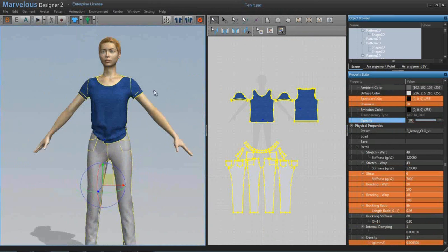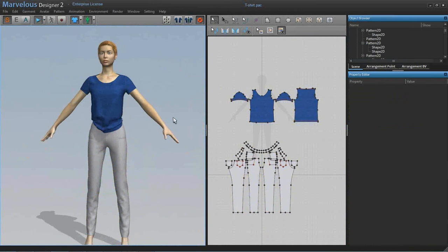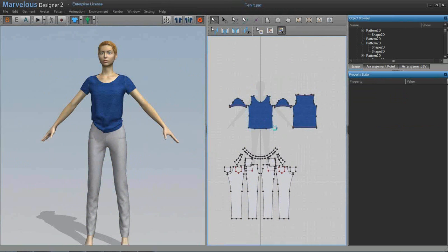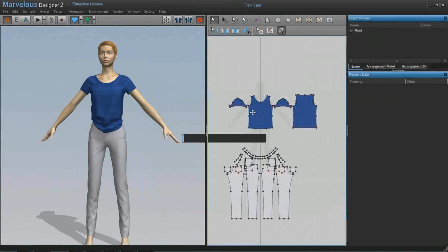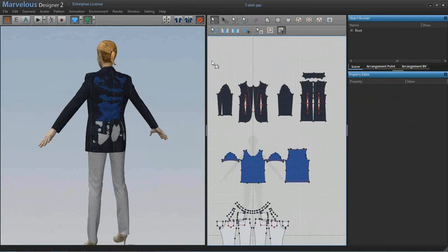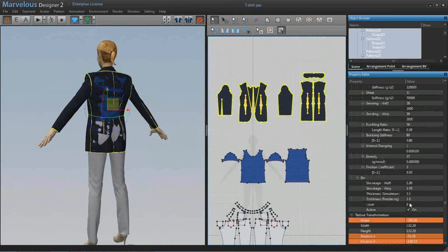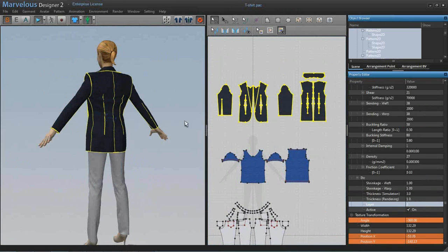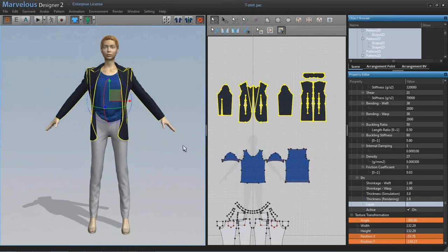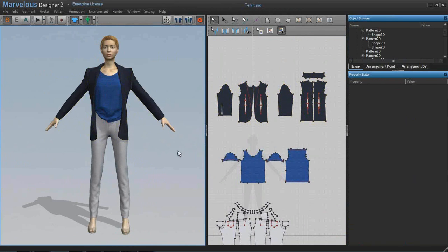Okay, I layered the 2 garments, and if there is enough space between garments, you can add more and more. I'm going to load the jacket. There are also intersected parts. Select this jacket and change the layer. Like this. Okay. I coordinated the 3 garments very easily.